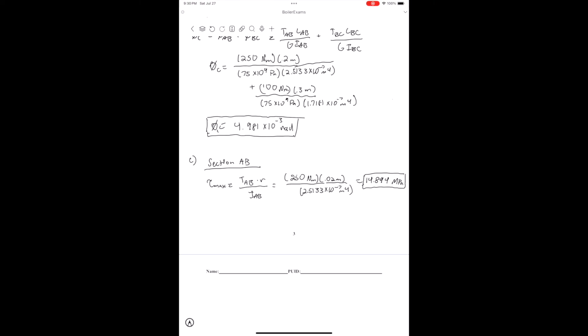And then we have the formula for tau min, the minimum shear stress, as being R point over R surface, and that should be R point being the most internal point of the rod, so times tau max, and that's why we found tau max first, because we needed it in order to find tau min.